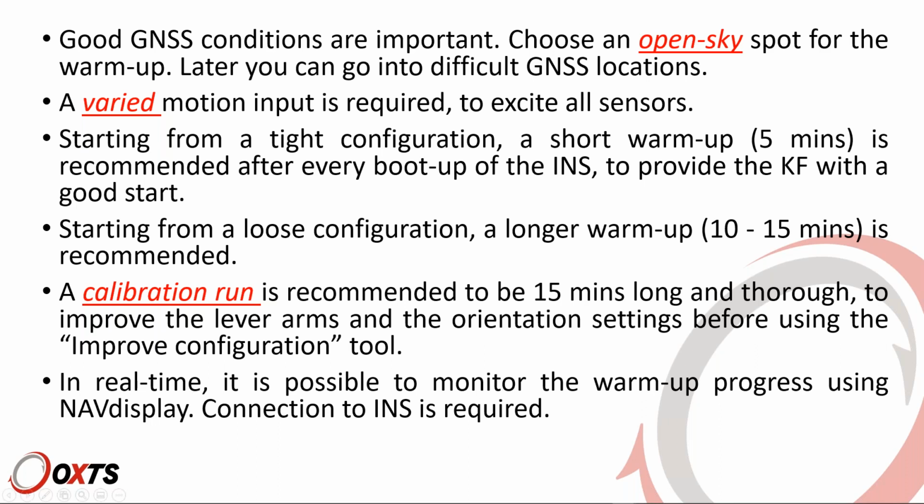So you do a calibration run. This is a warm-up of the full 15 minutes, if possible in an open sky environment. Then you use the improved configuration tool and you upload that configuration. The good thing about it is that you only need to do it once, unless you move stuff on your vehicle. If the antennas and the INS stay in exactly the same spot all the time, then you only need to do the calibration run once.